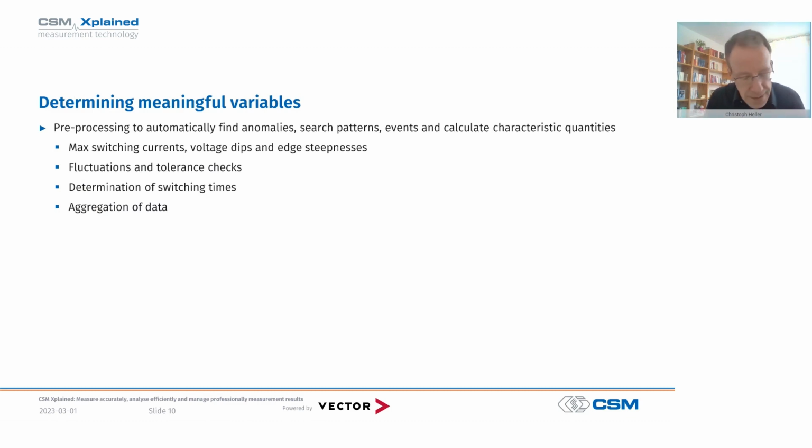So only a few more hints. Pre-processing, this data analysis engine, analyzes every uploaded file. This is the area where your experts should provide the analysis routines, because this is the point in the overall data handling flow to get the really important information. Some customers use this to detect maximum currents and voltages, or they count the gear shifts, or they calculate average oil temperature in intercity test drives, or they get a clear indication of the switching times. And there they also have the possibility to aggregate data from other systems, maybe diagnosis information, to have it available together with the measurement file and the measurement configuration.